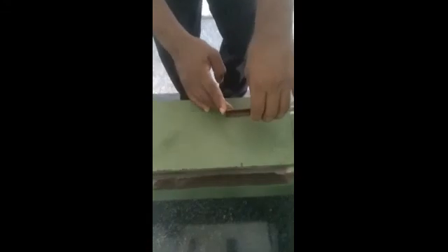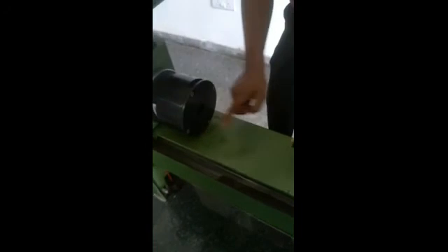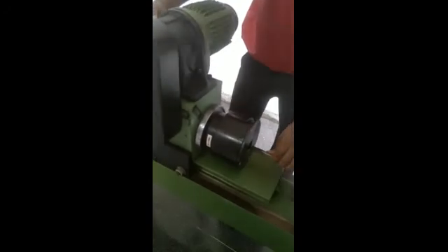so the center drill and the pointer should match with each other. Then we have to tighten this jaw. That is one side clamping. On the other side, if you see the second side of the specimen, there also there is a center drill. Inside the chuck also there is a pointer, and that pointer should match with the center drill. So we have to push this setup forward and match this.